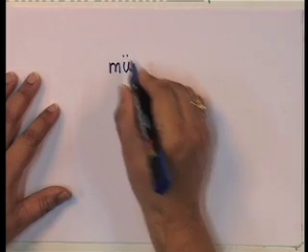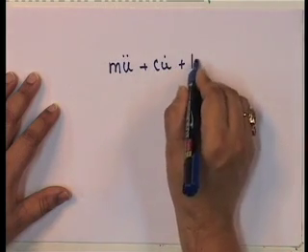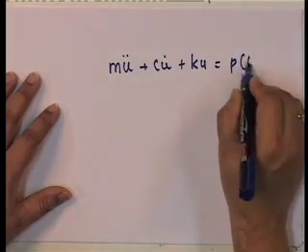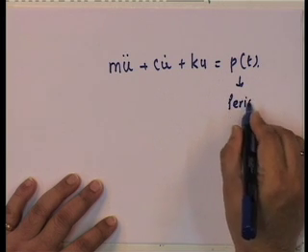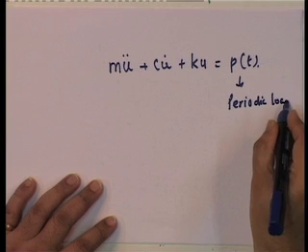Okay. Now, what advantage do I get by taking P of t to be a Fourier series? Well, let us see. Let me look at the response of a structure to a periodic load. In other words, what am I doing? I have a periodic load, and I want to look at the response of a single degree of freedom system to this load.